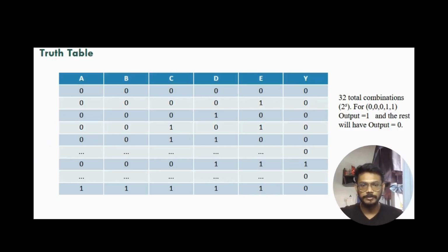So this is the truth table of our design. Particular to the inputs and the output that we set, when the water level needs the pump on, the output should be 1. We have 5 inputs, so the total combinations we could get is 32. We are focusing on A, B, C being 0 and D, E being 1, so the output should be 1. The only combination relevant to the input and output that we set is 00011.